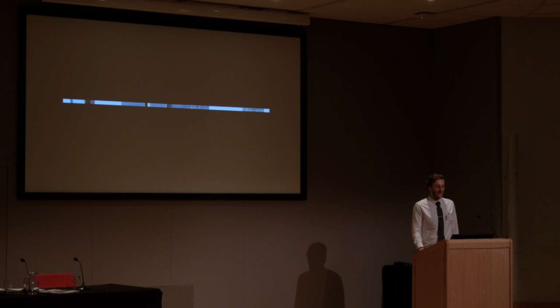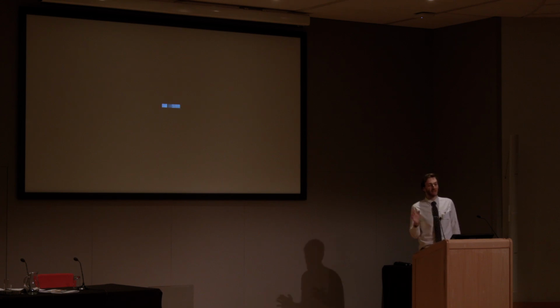So we have an issue on the 30th story. The first thing we do is cut off 31 and above and 29 and below. And we know that the issue occurs in a room in the middle of the building, and it's related to two of the exits. So we cut off everything else other than our room of fire origin, maybe a connected corridor or two and a couple of exits.